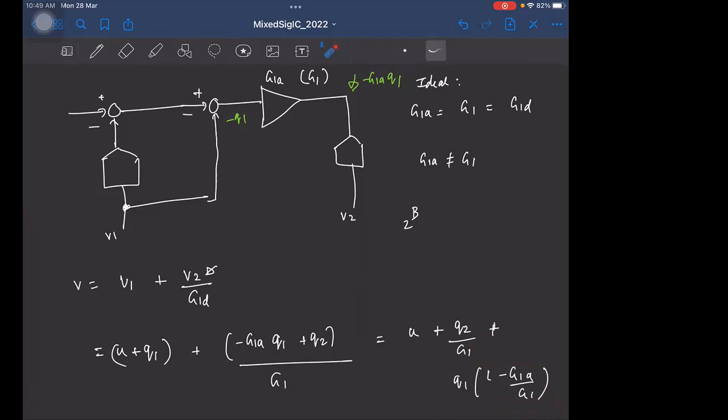Okay. The gain you realize here must be in the analog domain, right? Because the input is an analog signal. And of course, here I have a DAC, I didn't write it. So this is an analog signal, which means you need an amplifier here that amplifies the analog signal. Whereas when you recombine the outputs, these are all digital bits. So there you have a digital gain, right?